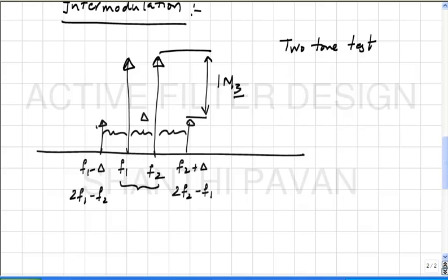Beyond the band edge, what is happening? The filter is filtering stuff off, so the node voltages are decreasing, which means that the amount of nonlinear currents that these transconductors are injecting will also reduce. It is indeed filtering the sum of the tones. If the two tones are at frequencies beyond the band edge, the peak voltage swings at every node in the filter will start to decrease. If the peak swings at nodes in the filter decrease, then the nonlinear currents injected by the transconductors must also decrease because it is proportional.